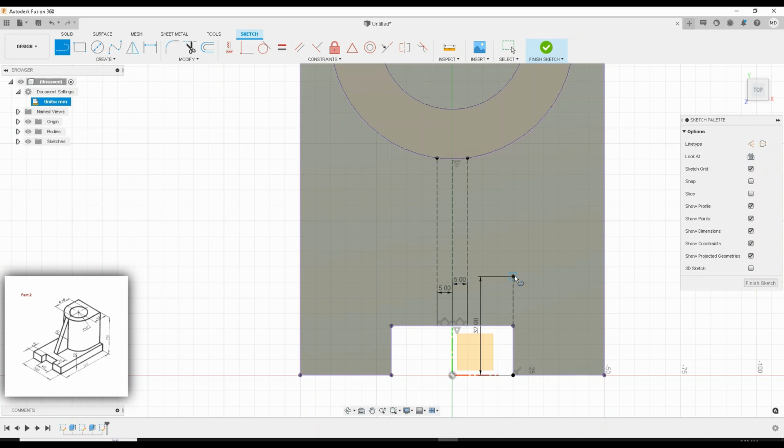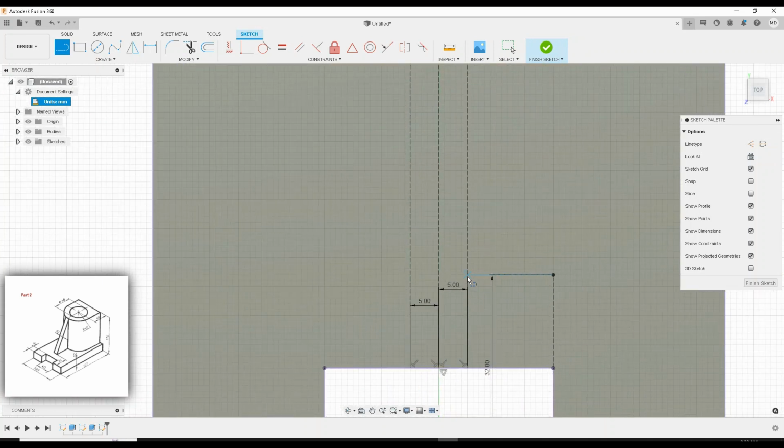And now from here, we're going to drag, because we already set that parameter. We know that's 32 mil from this segment to the segment we're going to place here. So you just kind of snap to it, go over, and you see how it ran into an intersection. Left click, and then left click again at this intersection.